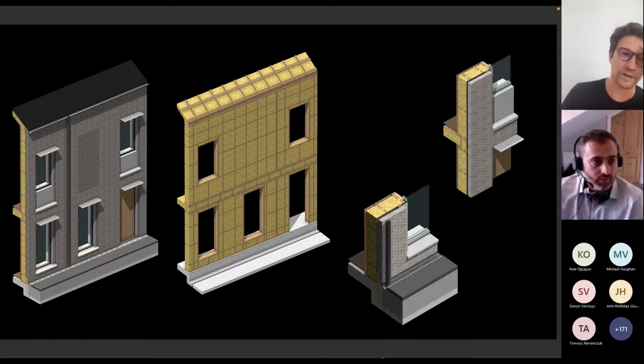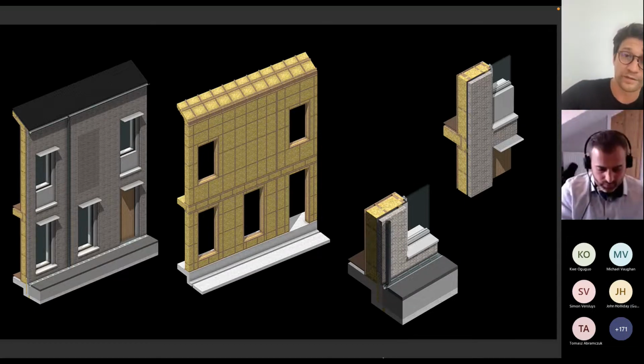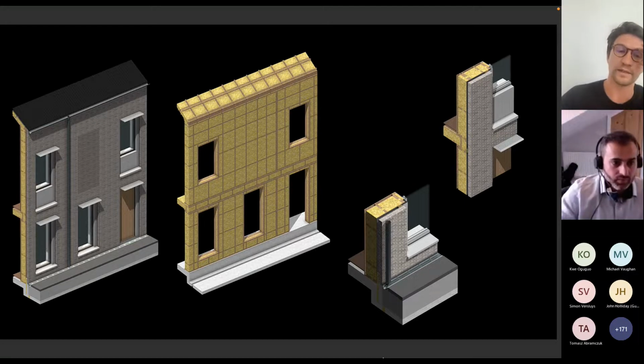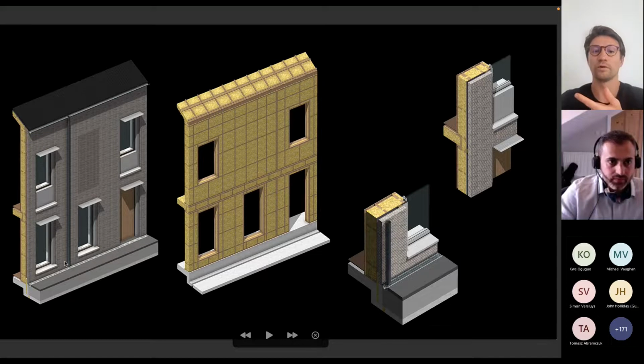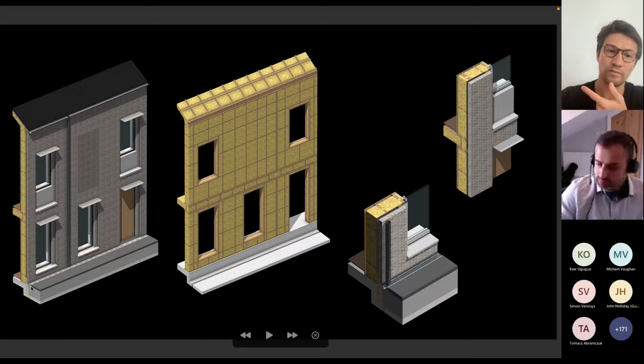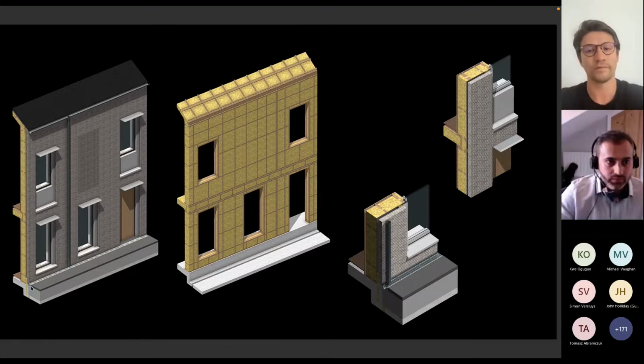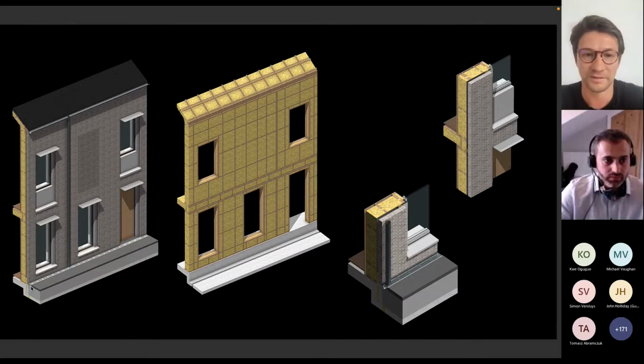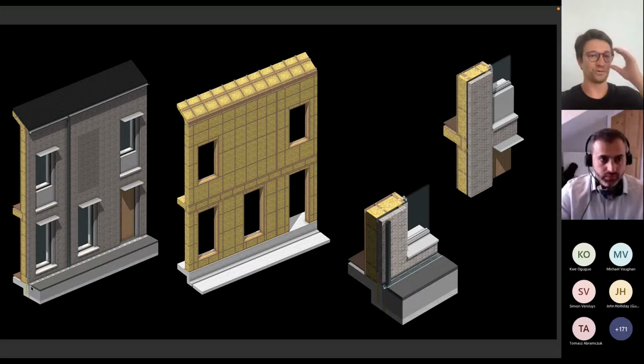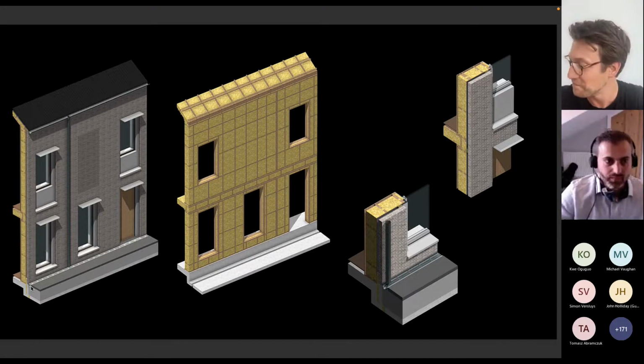That would be the best way of achieving the brick facade, the most cost effective and the most sustainable, in a low-rise building, low-rise timber frame, not using metal to support as much as any other one would. So low-rise masonry veneer on timber frame would be the best, not carbon neutral, but the more sustainable way of installing it.